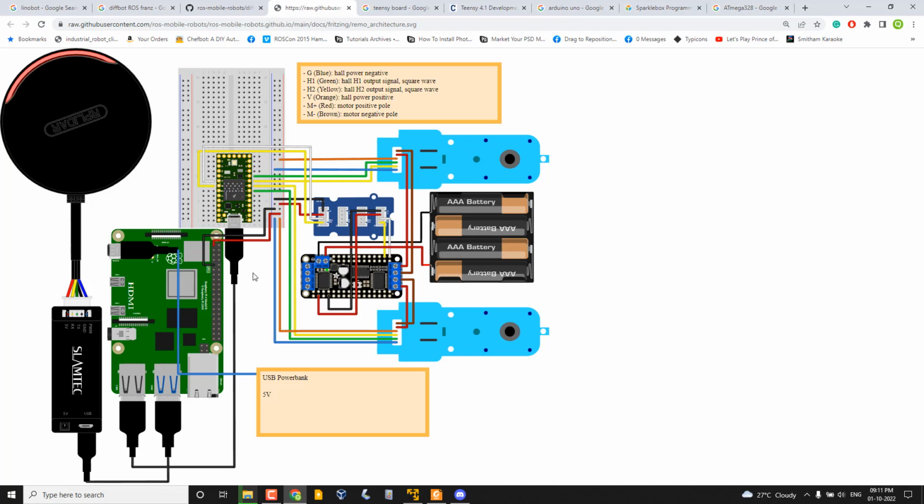So instead of working with the UART protocol, or instead of sending some characters to the microcontroller and reading the sensor value, in order to make the entire communication easy, we are creating another top level communication protocol. The UART is a base communication protocol, and using that protocol, we are creating a high level communication protocol.